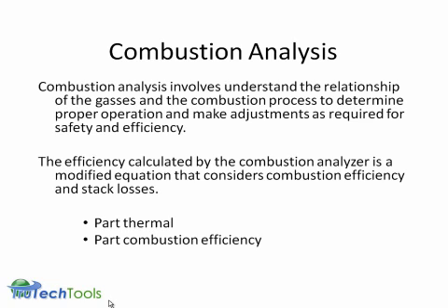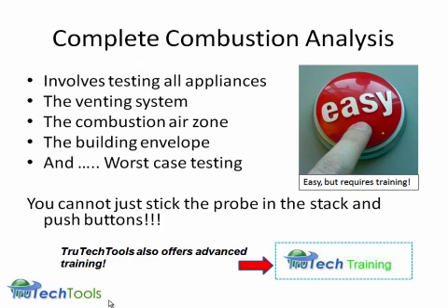Combustion analysis involves understanding the relationship of the gases and their combustion processes to determine proper operation so we can make adjustments as required for safety and efficiency. The efficiency calculated by the analyzer is actually a modified equation, and it's part thermal and part combustion, but it considers combustion efficiency and stack losses.